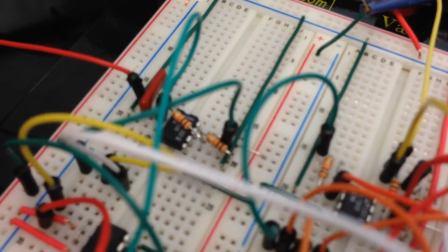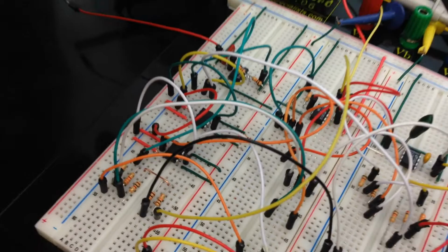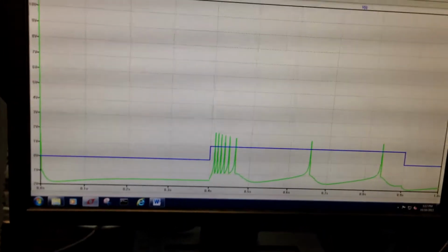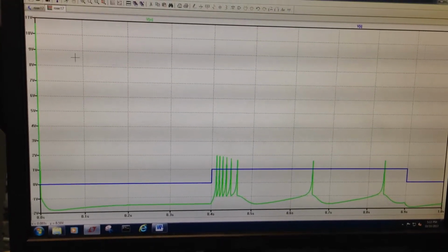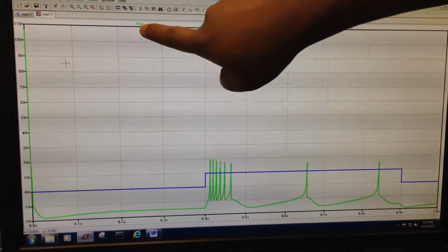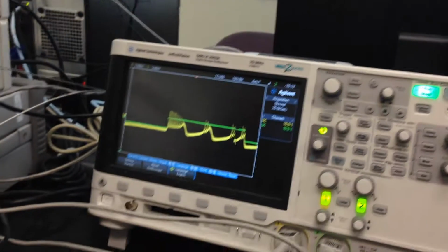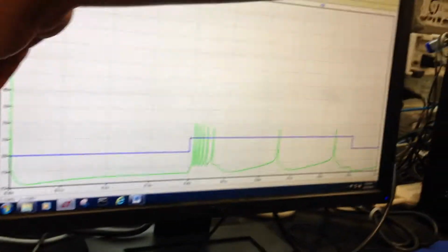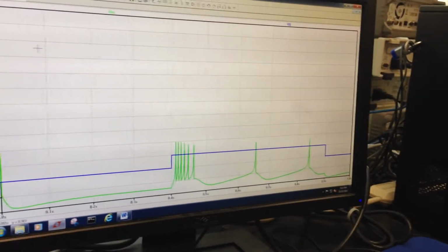Once we had this running, we were able to have our oscilloscope model waveforms, and then we also have our LTSpice schematic simulation. For the LTSpice simulation, once you run the simulation, we are able to get this output for the X output at a 1 volt input pulse. As you can see, the oscilloscope output is quite similar to the LTSpice simulation, making it a possible circuit.